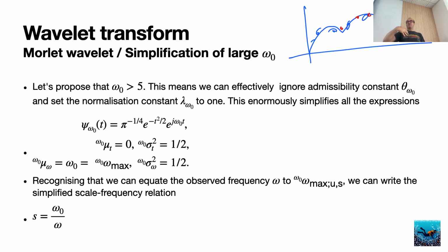But when we are doing long-term experiments, we select one wavelet and we say, okay, this is our tool, and we are going to calculate every impedance spectrum with the same tool, and all the points will be on top of each other. But if you start changing it, they will start to wiggle back and forth. That's the effect you're going to get. And how do we go from frequency to scale?